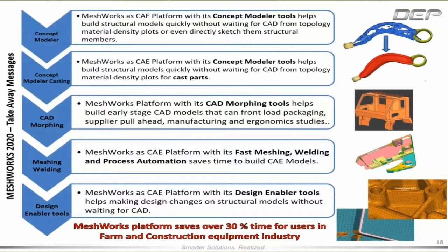That is where making design changes on the mesh itself without CAD comes in handy. And in addition to that, we are able to make the CAE model parametric. Maybe it is the wall thickness changes or the number of tetra ribs in the powertrain or driveline components, or it is the seam weld length in the axle driveline kind of components, or maybe it is the wall thickness changes as we talked about in the transmission housings or the auxiliary gearboxes of our farm equipment.